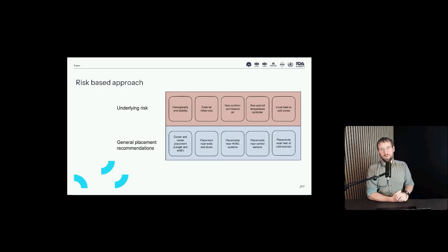That is actually what we're looking for, but in all cases, the air temperature will change before the product temperature does. So in that case, you will have fewer spikes when you use a dampener. If you don't know what a dampener is, you could take a jar or a vial of, let's say, glycol and insert the sensor into that. It will take some time.